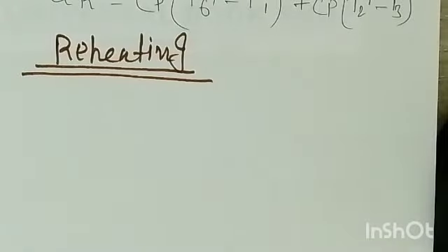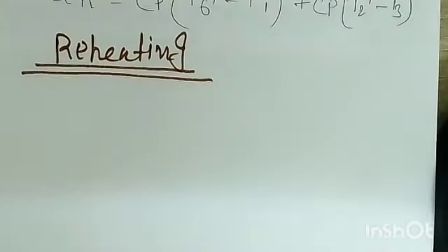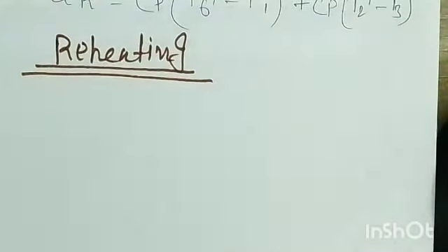In intercooling we are splitting the work input of a compressor, and in reheating we will provide the stages of turbine, right? So reheating is how we can improve the specific work output, by splitting the expansion work. So in intercooling we are splitting the work input of a compressor, and in reheating we are splitting the expansion work to improve the specific work output of a turbine.